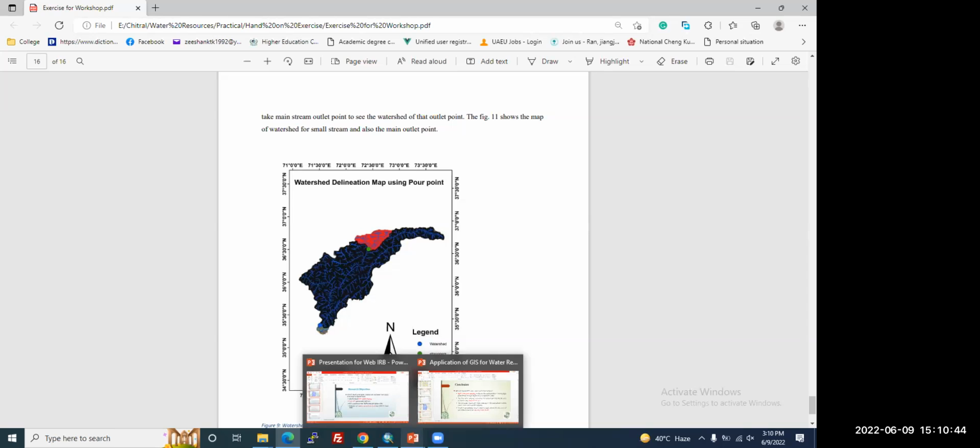It says, sir, if we want to run this hydrological modeling, the only data I need is the DEM of the study area, right? Yeah. At the moment, if you want to do watershed management, you only need the SRTM DEM. But with the passage of time, whenever we are using, for example, discharge data and calculating some water modeling, then we need some other parameters as well, for example the discharge data from gauges and some other data for streams. For the current stream flow and hydrological modeling, we only need a digital elevation model, and it's better to use the SRTM model, so it will be easy for processing.